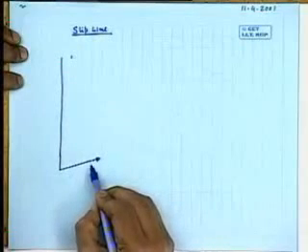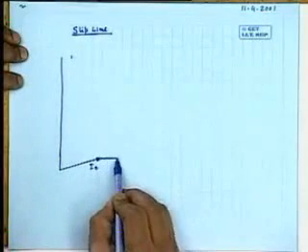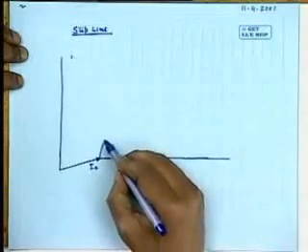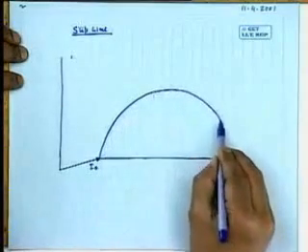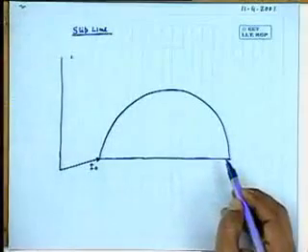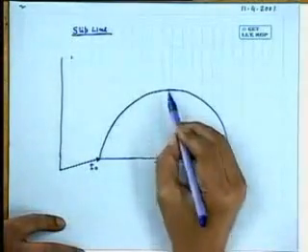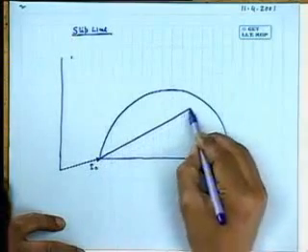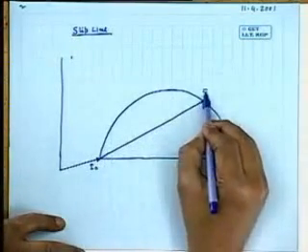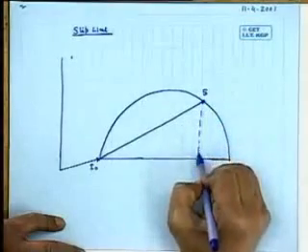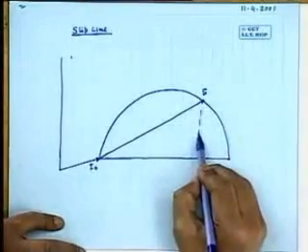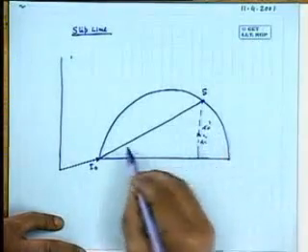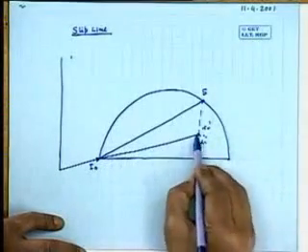So once again, this is the no load current, I0, and this is, suppose, your circle, and this is suppose the standstill condition, operating point S, and this length is divided in the ratio R1 is to R2 dash, so that this line will become your torque line.